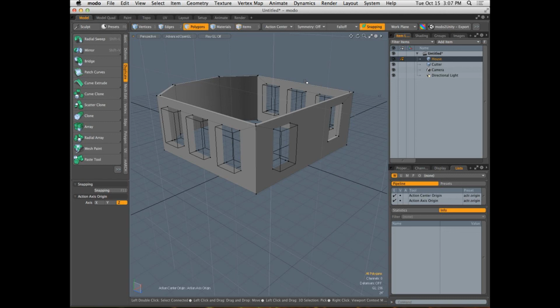Explore the other operators. We have the axis slice and of course the traditional Boolean tools. I like solid drill because it gives me the most options. Okay, it allows me to determine what the next step is going to be. I'm not a big fan of having it automatically delete all of those polygons on the interior of the window. It took out a certain level of control in my modeling operation. What if I wanted to make like a groovy little windowsill? What if I wanted to create some rails and some other window component types? Well, without those polygons there, I would have to infuse a couple new steps back into the mix.